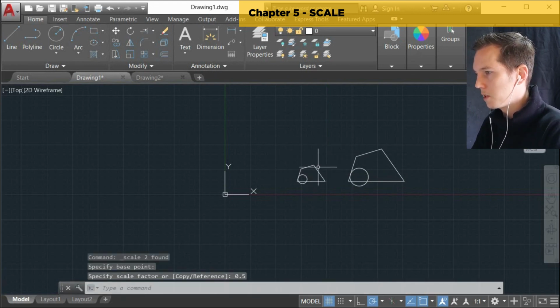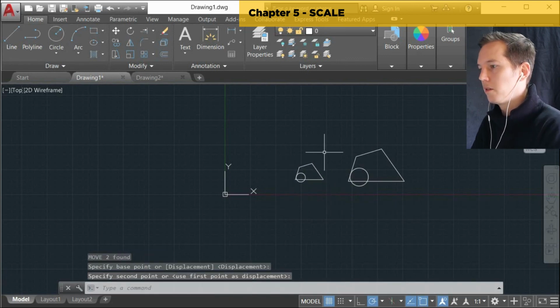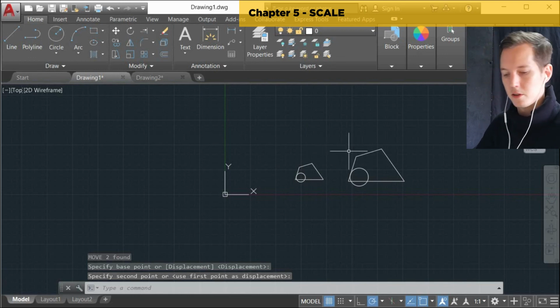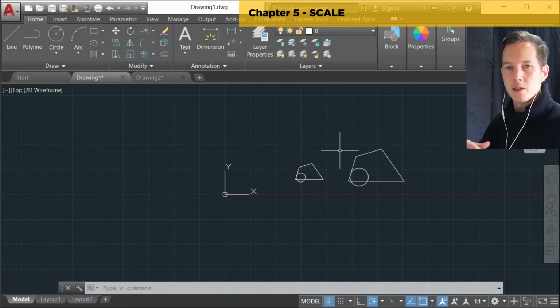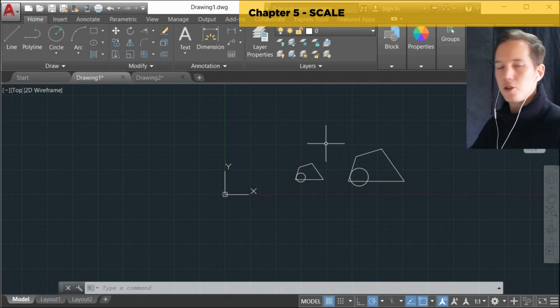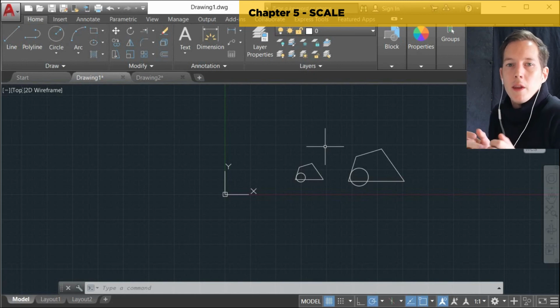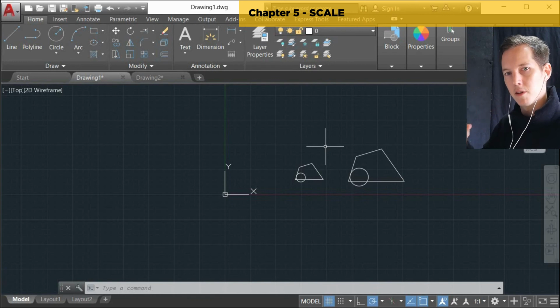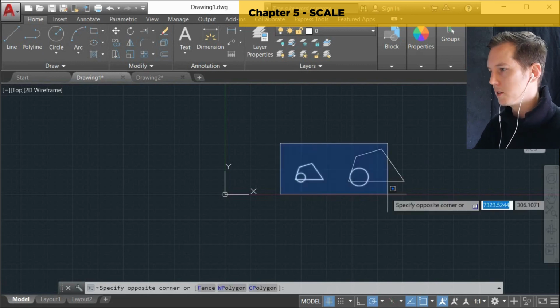So now you see that's the original. I've made one that is now half as big. So that's a good way to use the scale tool. You can do it by clicking, but you'll see for some reason it makes the mouse go AWOL and gives you this huge scale factor that you'd never use. It's easier just to type it in. But just remember, 1 is no change at all. If you scale something by 1, it doesn't change. That's its original size. So you have to think of everything as relative to 1, 1 being 100%, 2 being 200%, 50% being 0.5, etc.